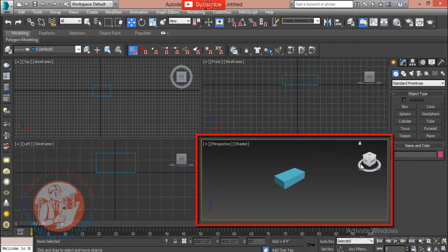Go to Home View. The ViewCube also lets you click and drag on the cube to rotate the view around. You can also click and drag on the base ring to spin the model about its current orientation. Above the ViewCube is a small house icon. Clicking this icon changes the view to the defined home view.